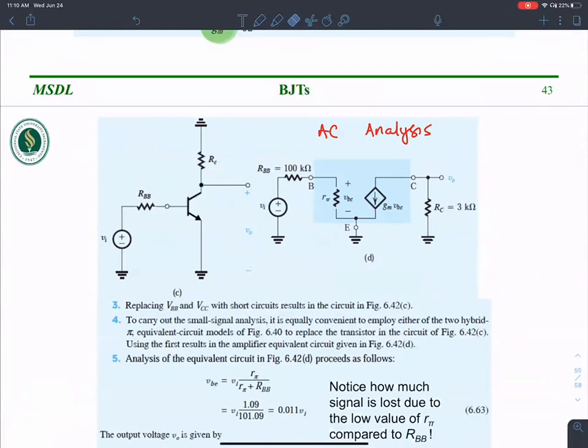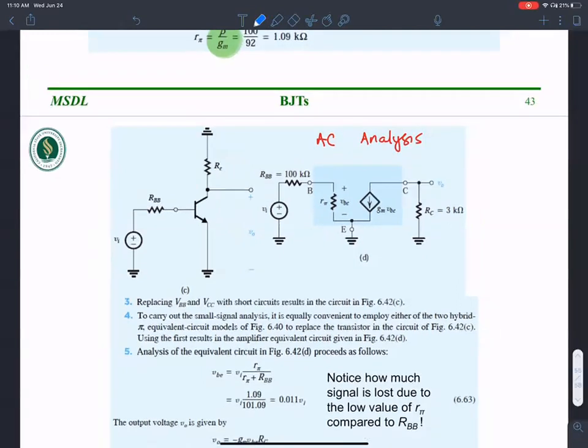So you have to be careful that you're properly biasing with enough voltage headroom and legroom on VC, so that even if your signal swing is large, you're not leaving this linear or active region of operation. There is a trade-off. All right, so that's the idea of